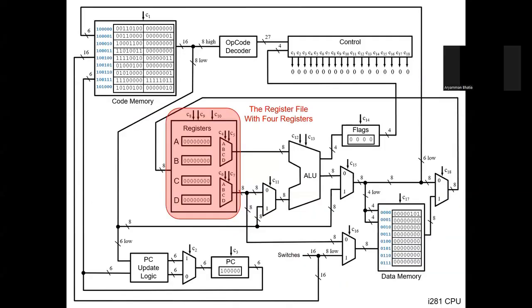Like I talked about the register file, that register file is what is accessed for any dynamic computation. We pull data into that and then compute, and we store the result in one of these registers, and then we push that data back out into the data memory if need be for the future, right? So all the magic is happening in these registers. The data memory is just for storage. The code memory is just to process the instructions.